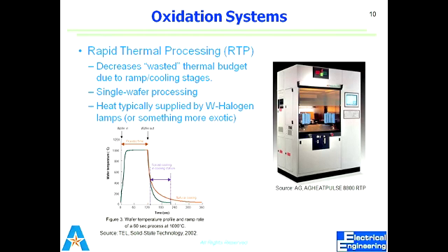at 1000 degrees centigrade for 1 hour, while the other wafer has been at 1000 degrees, the same temperature, in the same furnace for 2 hours, for a greater period of time. So the second wafer has got greater thermal budget because it has been exposed to 1000 degrees centigrade for a longer period of time. So the time of exposure to a certain high temperature is what counts as your thermal budget. That tells you what your thermal budget is for this device. Okay, so the time for which you expose your device to high temperature defines your thermal budget or thermal exposure.